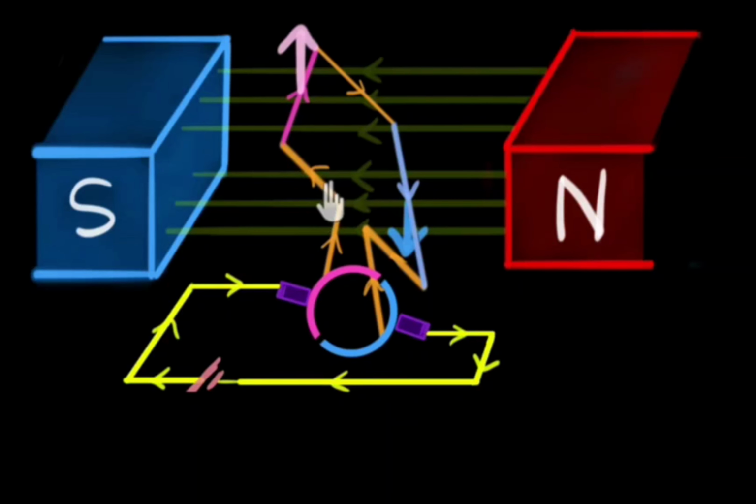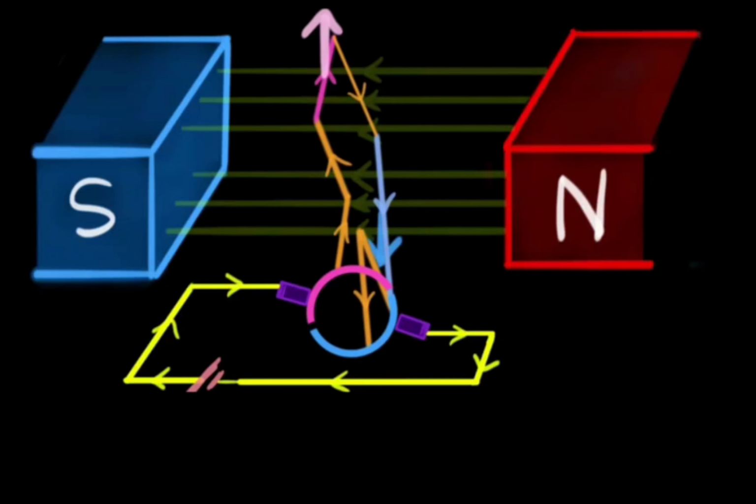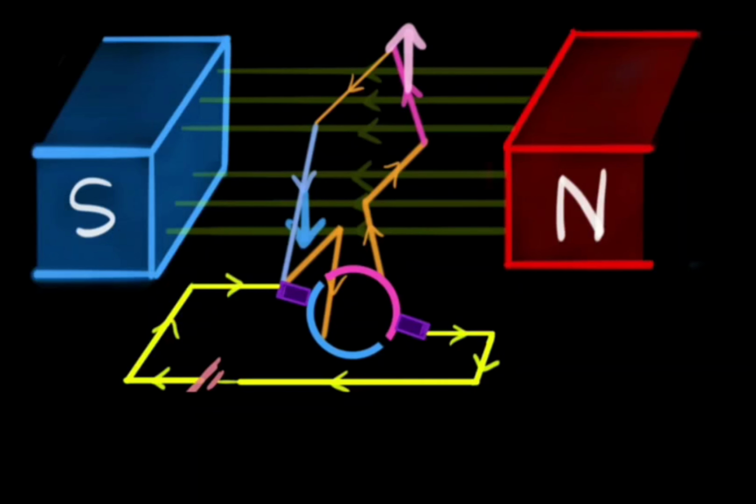These forces also give rise to counterclockwise torques. If the air gap flux is assumed to be radially directed at all points, each force acts tangentially and produces a turning moment equal to the force multiplied by its lever arm, the radial distance from the center of the conductor to the center of the shaft.